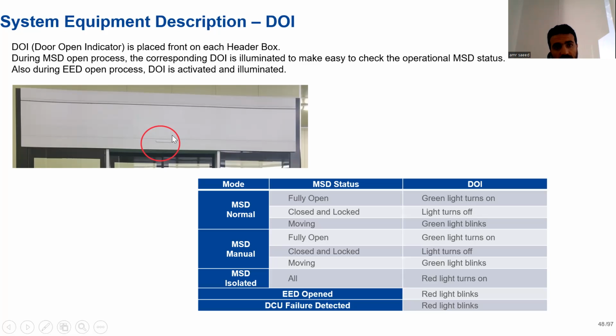It's a temporary mode. You cannot leave PSD system with isolated for any door, because of safety for passengers. Maybe one passenger can open the door while isolated and go into the track while the tram is moving.